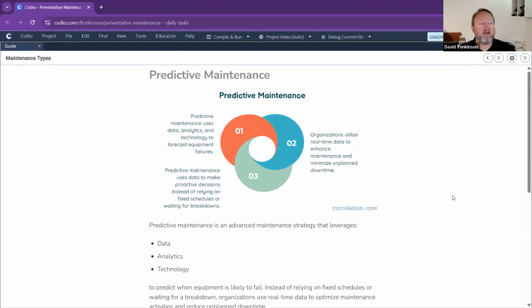Fire extinguishers usually have a best buy date, but I tend to put that into preventative maintenance because preventative is basically you're checking on a regular occurrence. So you will normally check your fire extinguishers every 6 to 12 months, depending on the requirement. Whereas predictive, you're actually waiting for some information to come in and say, actually, you need to do something.